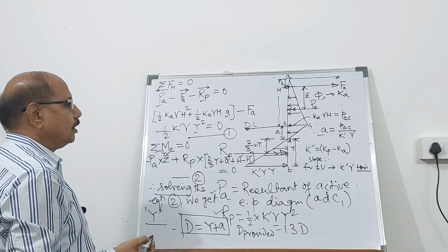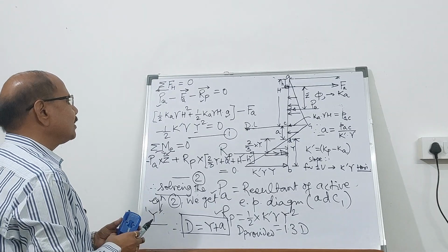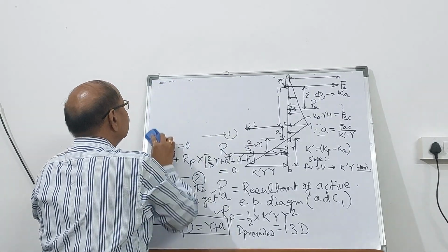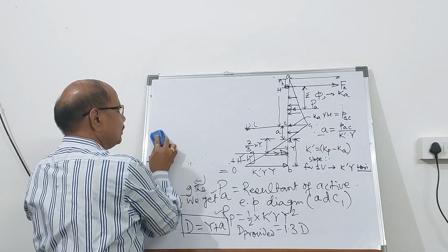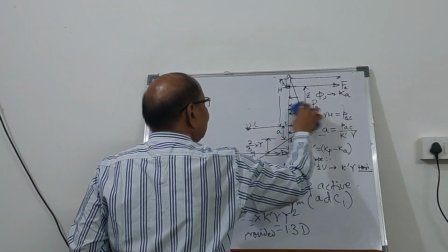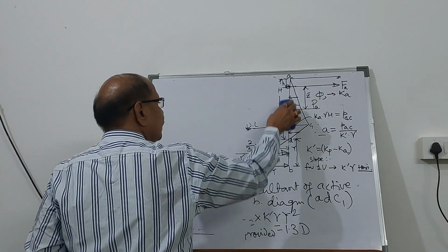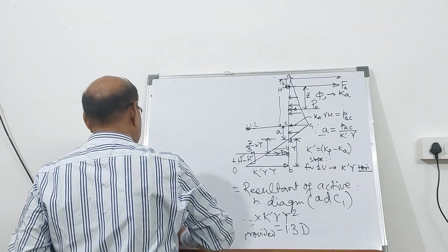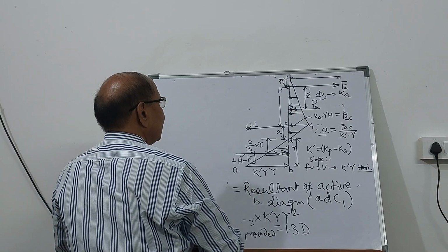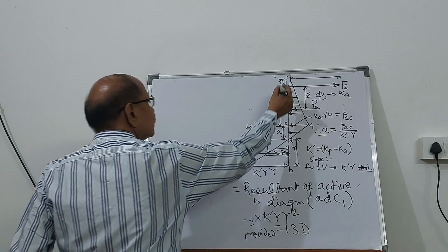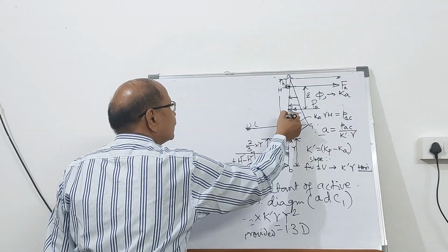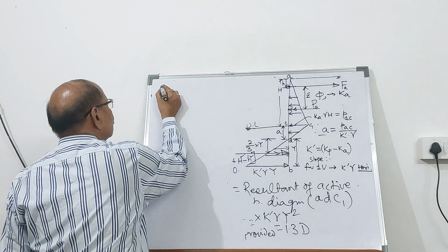So whatever D comes out from the calculation, increase it by 30%, and that is the magnitude of the depth of embedment. Now, so far as the maximum moment is concerned, as you have seen in cantilever sheet pile, here there is going to be an additional force over here. So PA acting this way and FA acting this way. So the point of zero shear force, or the location where the shear force is going to be zero, is going to be between this C and E.